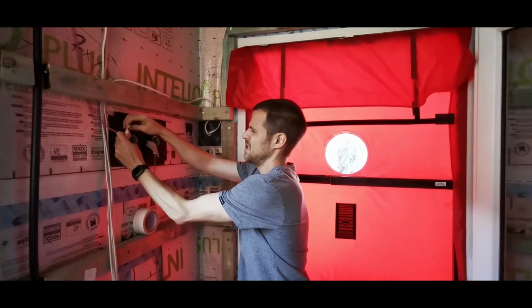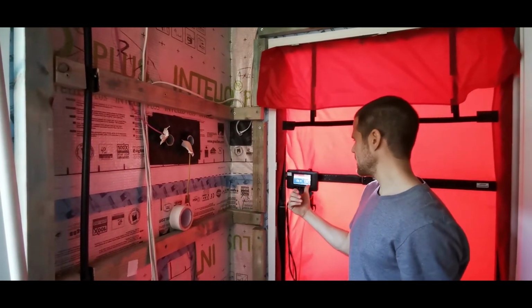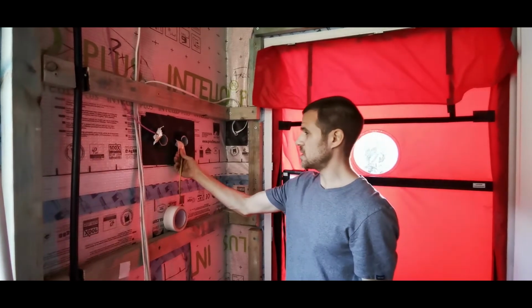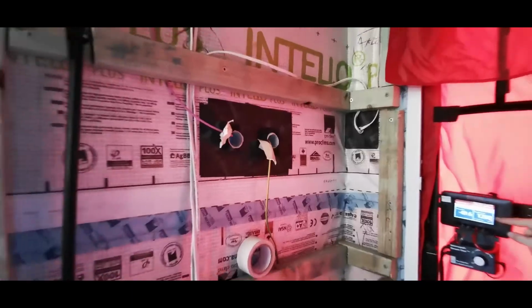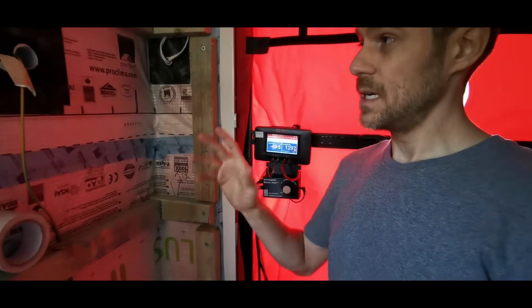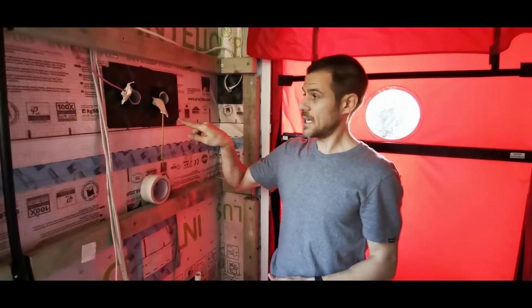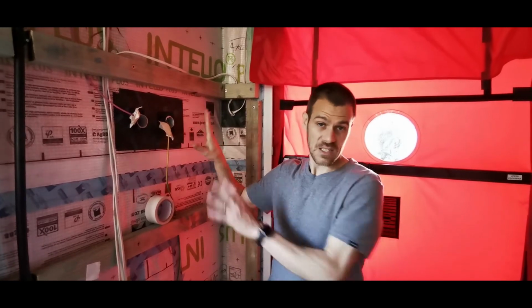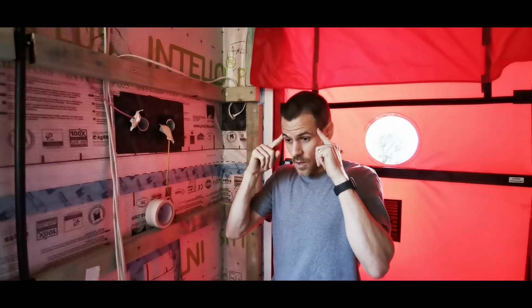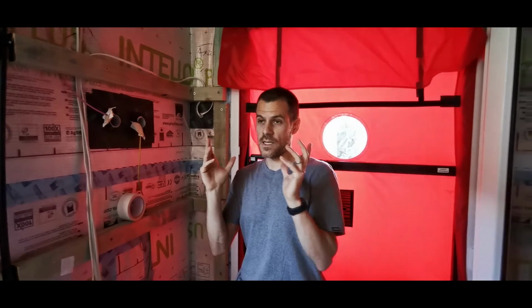So if I take this off for the moment, and just see, before I take these up, we will try to adjust for 50 pascals. We'll see how much these leaks count. This is about 1280, 1285, something like that, which is about 50 cubic meters an hour coming through these two things. So that's right there. You can see leakage and you can see how much that's worth. When you're going around a passive house, you can say, okay, where is 1,000 cubic meters an hour of leakage coming from?